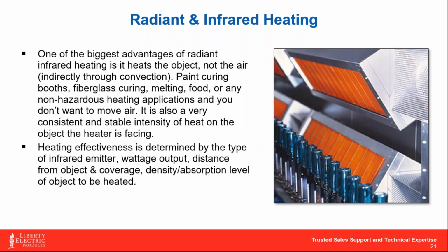So if anything, when we look at this, the big advantages are that, again, you're not stirring any air with it. They are popular in things like curing booths. Personally, I think that they work well for paint curing, if you can get the power connection brought back to the quench-proof or spark-proof box, if you're doing it for, say, automotive, where you've got flammables involved. To the best of my knowledge, there is not a manufacturer yet that actually makes a Class 1 Div 1 rated radiant heater. So they are a bit rare.